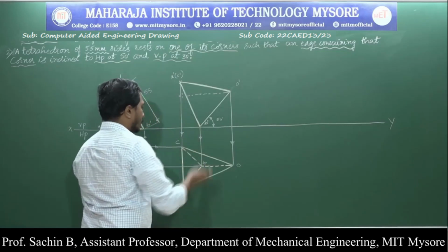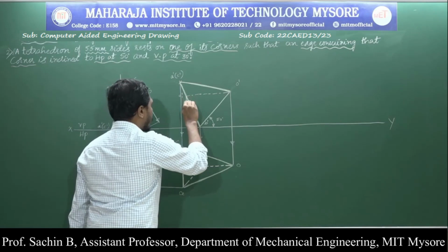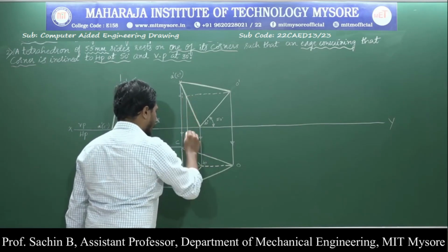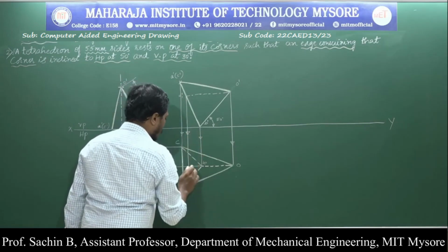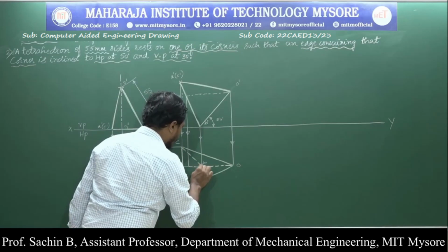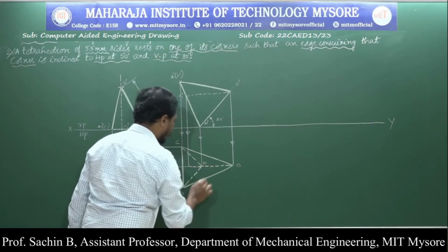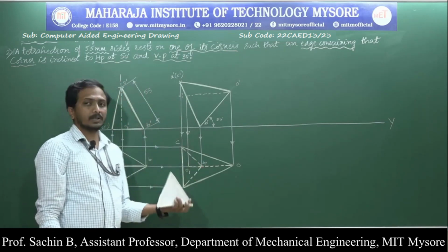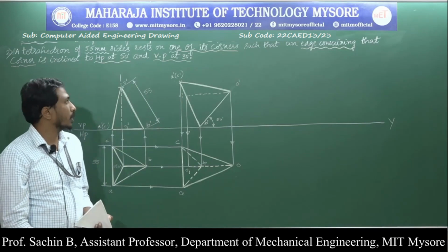Next I will go for drawing the projection line from the O1 dash point. Now here the axis is present, so I will go with the chain line. This is my O1 point. This is the second position top view of the object.